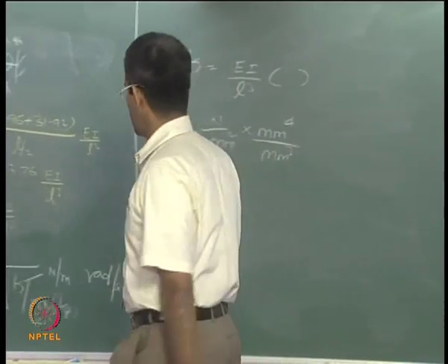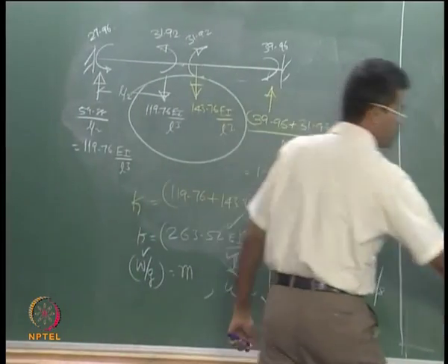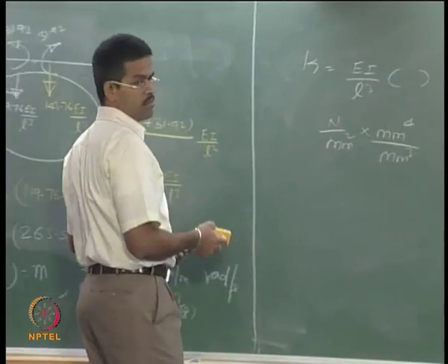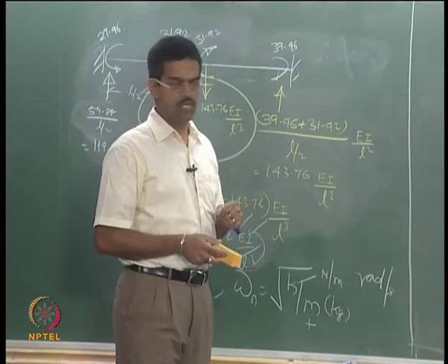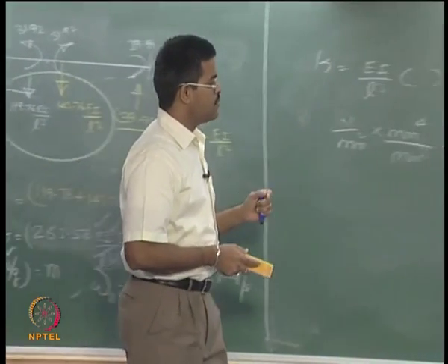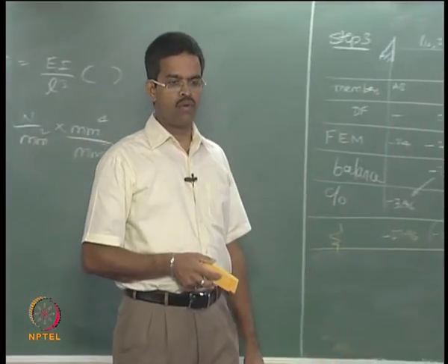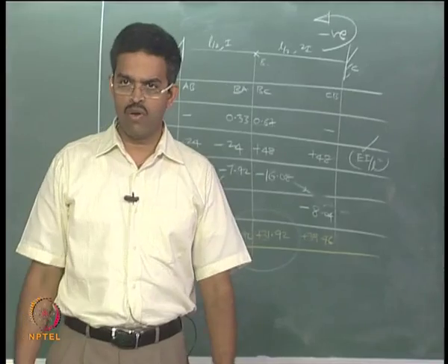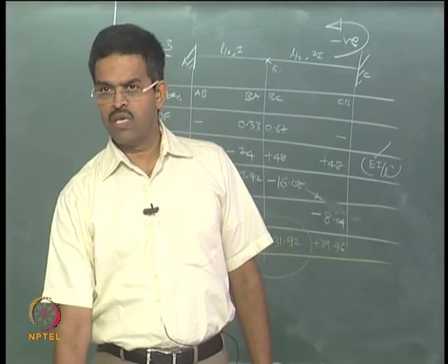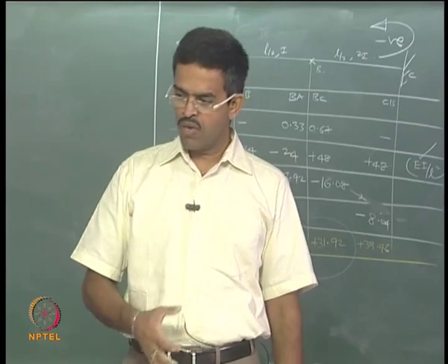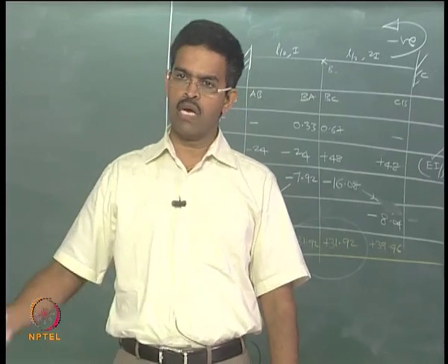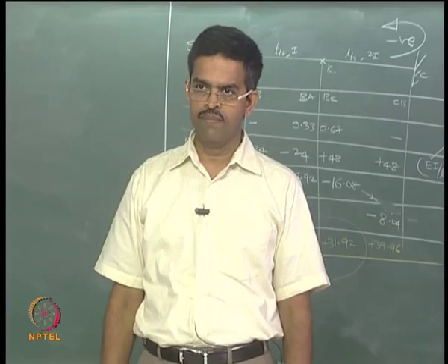So, let us derive what we call the lateral stiffness of any given member. We are focusing on derivation of stiffness and mass matrices, because for single degree if you understand how they are done, for 2 degrees and multi degree it will be easy for us to work further, because we will have no confusion in arriving at the mass and stiffness matrices. We can work further on things which are more complicated than getting m and k.